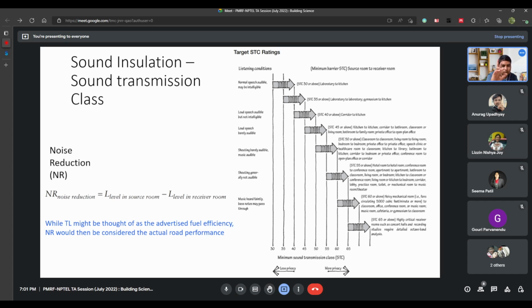In acoustics, there are two different concepts you have to consider. One is that you have a room and a space, and the surfaces inside the space have to be treated in such a way that you receive good quality of sound. Another is looking beyond the room. You have a sound source in this room, which might or might not be desirable in the next room. So how do you barricade the sound in a particular space so that it doesn't propagate into the outside space? To measure that, these other values are used.